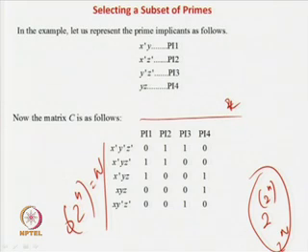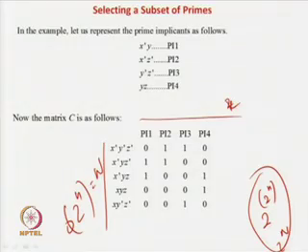Okay, so like all other problems, such as the scheduling problem, they were exponential in the number of steps or exponential in the number of operations and so forth. But in this case it is doubly exponential in the number of variables, or exponential in the number of terms. This is the problem space. So these are your prime implicants and these are your min terms. This problem space is of the order of 2 to the power n, where n is the number of variables. And to solve the problem, where this is capital N, it is 2 to the power capital N. So in the other way it is 2 to the power 2 to the power n.